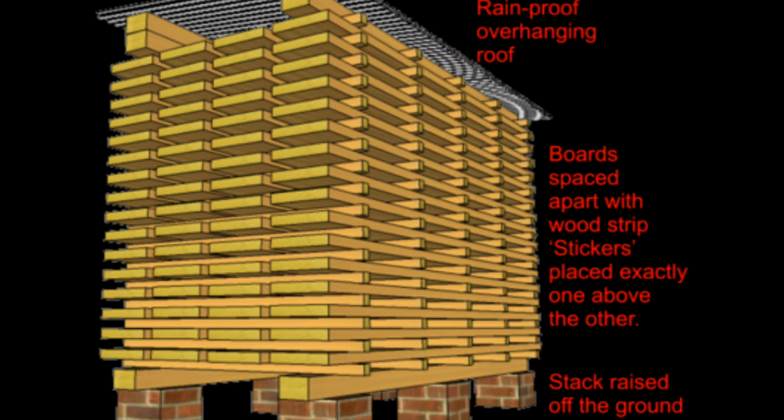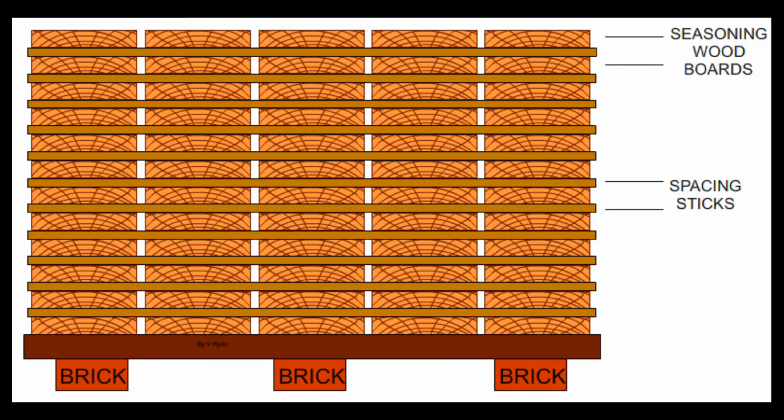It involves the process of exposing the wood to air and sunlight. The seasoning of timber is carried out by natural air. Hence, it is also referred to as air seasoning. The timber pieces are stacked either horizontally or vertically in such a way that there is sufficient gap between the sections for air to pass through.